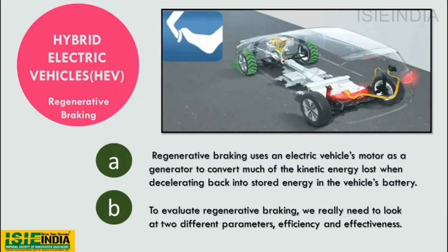Adding to this, driving conditions also have a large impact on regenerative braking. You will see much better effectiveness of regenerative braking in stop-and-go city traffic than in highway commuting. If you are repeatedly braking, you will recapture a lot more energy than if you simply drive for hours without touching the brake pedal.